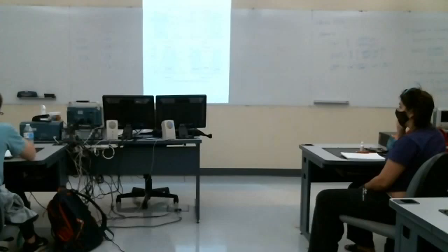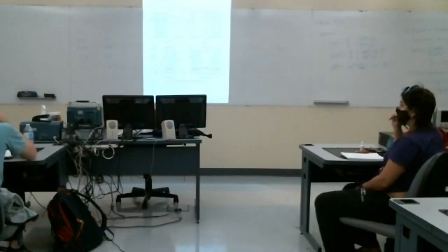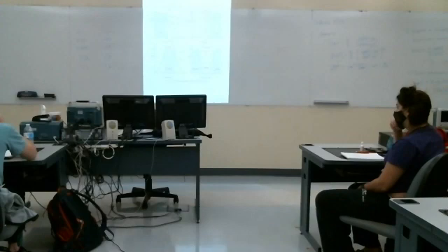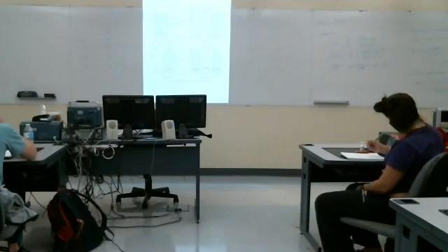So essentially, we're going to ignore this term for omega values to the left of omega c. And so what this reduces to is 20 log of square root of 1, or 20 log of 1, which is 0. That's really easy to plot. That's just this line.